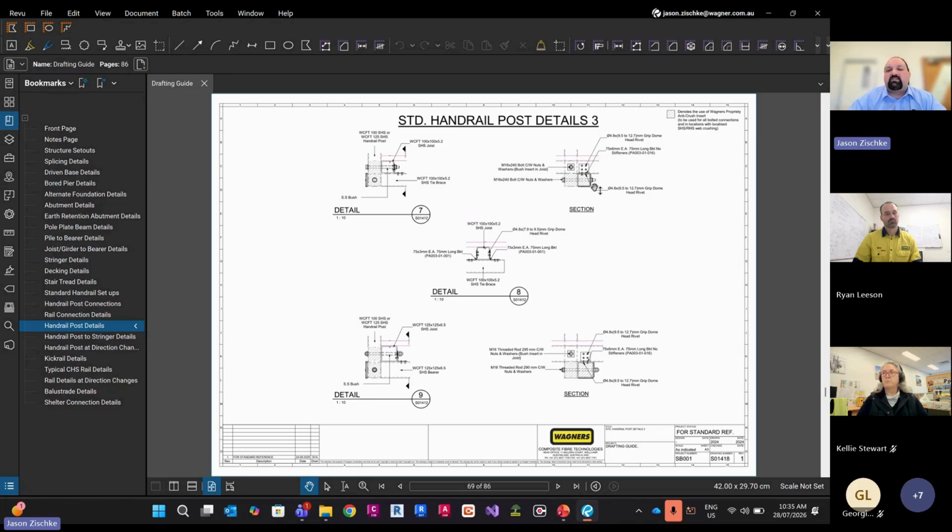First, we had stiffeners on this bracket. Now we generally don't have stiffeners on the bracket unless we have high handrail loads greater than your standard 0.75 kN top rail hand loading. Then we'll generally have beefier connections down here, but for standard Australian Standard loads, this is all catered for in that development of design.